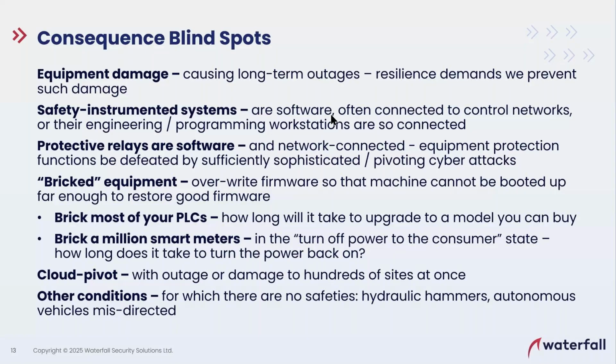They say, "Oh, I got this figured out. I got my protection systems in place. My equipment's not going to get damaged." What if the bad guys get into the OT network and log into each one of our PLCs and erase the firmware? What do you mean? Write zeros into the flash that is the firmware, and then they reboot the device, or worse, put the device into a loop that constantly writes zeros into the flash.